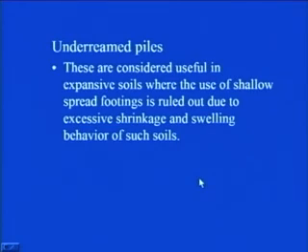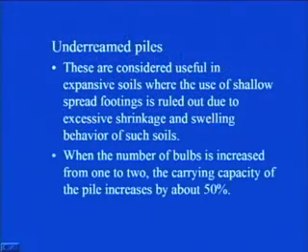These are considered useful in case of expansive soils where the use of shallow spread footing is ruled out due to excessive shrinkage and swelling behavior of such soil. You know that expansive soil, with the presence of water or with the increase in temperature, frequently either shrinks or swells. So, in that case the shallow footing does not serve the purpose. Therefore, deep foundations are usually recommended for such types of soils, and in those types of soils these underreamed piles have proven to be very useful.